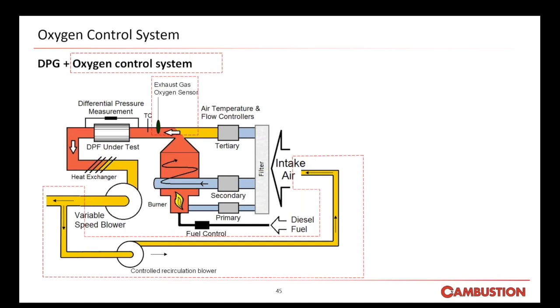The DPF inlet oxygen concentration can be controlled down to 2% in regeneration and loading conditions, simulating real diesel engine operating ranges. This is particularly useful for DTI testing, where you want to simulate diesel engine conditions more accurately than a steady state regen.